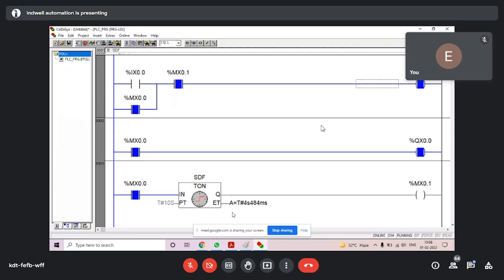And you see the timer has been running. Look at the screen. Accumulator, you can see 9 seconds, 10 seconds. After 10 seconds, it is off. One mistake you can make in ladder: double click, Control F7, and you have not switched off I0. What will happen? After 10 seconds, it restarted. So Q0 is not off, because you have not switched off I0.